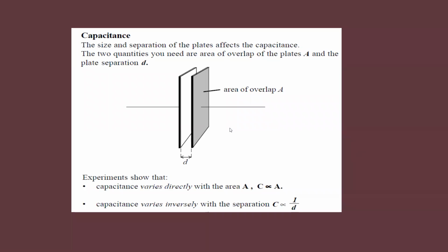Then the capacitance, how much charge is stored, also depends on the presence of any dielectric material. If you put any material between the plates of the capacitor, the charge stored will be higher. Why will the charge stored be higher? Because if there's nothing between the plates, like air, but one plate is positive, say maybe three positive charges, and three negative.